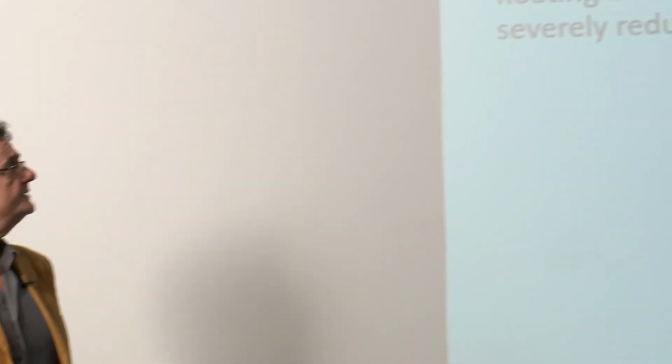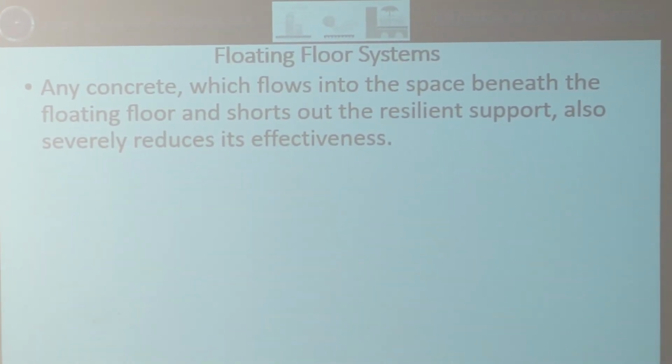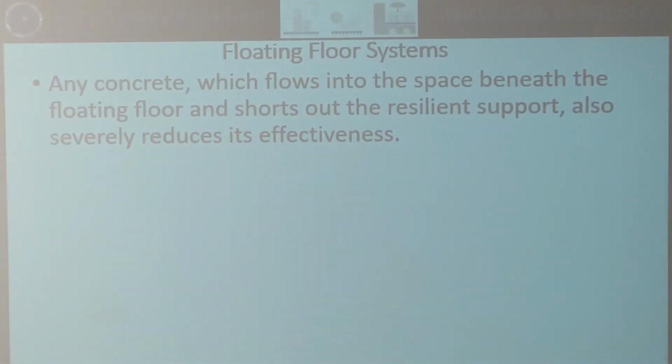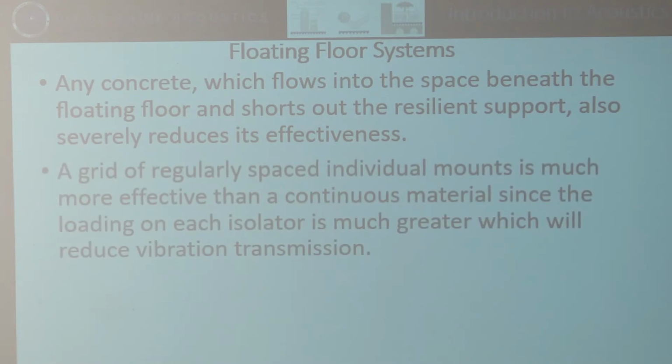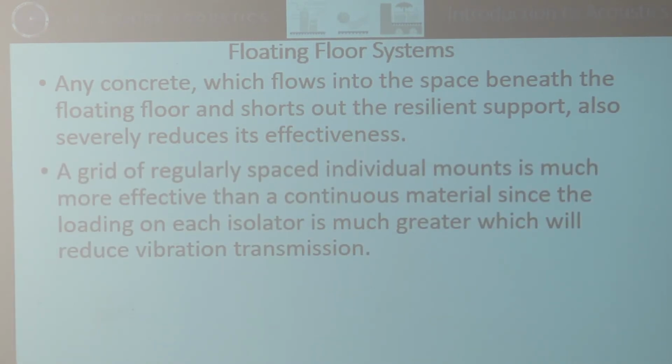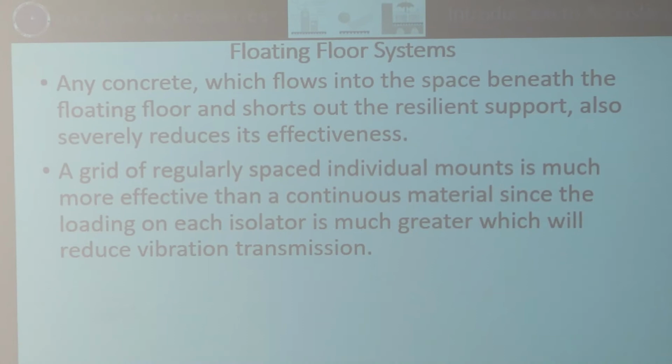Any concrete which flows into the space between the floating floor and shorts out the resilient support also severely reduces the effectiveness. As I said, concrete going into these air gaps is going to cause a problem. A grid of regularly spaced individual mounts is much more effective than a continuous material, since the load on each isolator is much greater, which will reduce vibration transmission. That is a good thing.